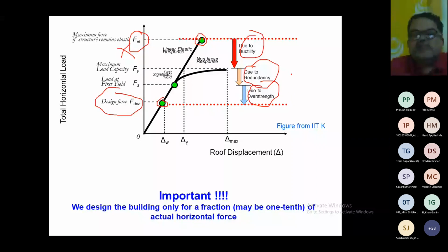But suppose 4 legs are required for equilibrium and I add 2 more; that provides redundancy. Buildings have a higher degree of redundancy, but bridges do not. In a simply supported bridge, if the deck or any pier fails, the bridge fails.